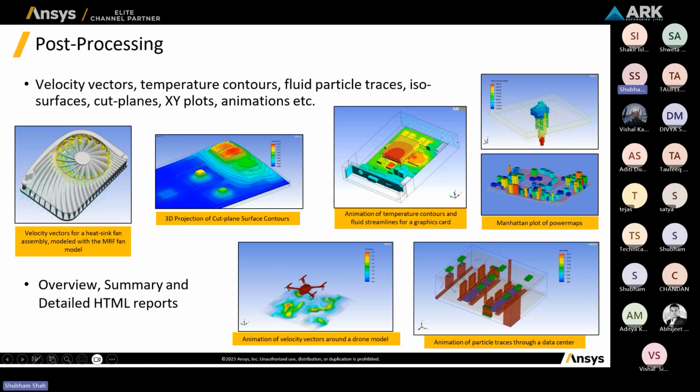The flow is entering from this direction and rotating in this particular manner. So the rotation side, you can see if you want to reverse the direction, let's say this is flowing in the clockwise direction and your flow should occur in anti-clockwise direction, you can reverse your RPM. So this is how you can analyze whether a fan is performing in a particular way or not.